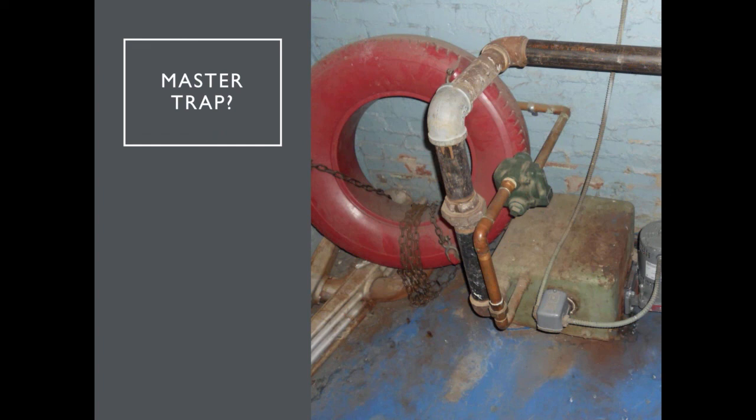They'll use an oxygen scavenger like a sulfite, which will trap the oxygen and take it away. You also want to keep your water temperature warm if you don't have any oxygen scavenger in there, because water at 70 degrees has double the amount of oxygen as water at 110 degrees. So you want to try to keep it warm or use an oxygen scavenger.